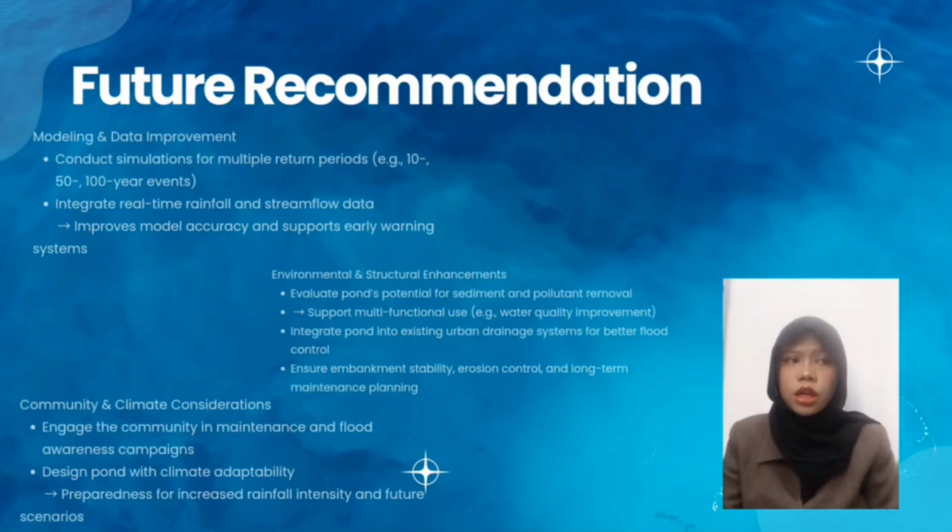For future recommendations, modeling and data improvement: conduct simulation for multiple return periods. Integrate real-time rainfall and streamflow data to improve model accuracy and support early warning systems.